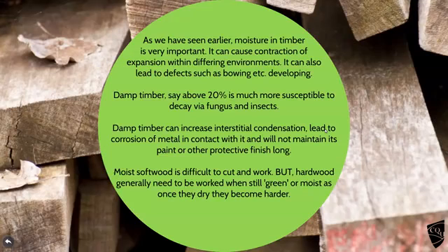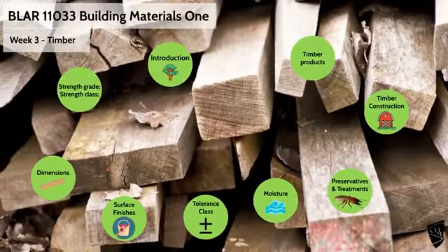Softwood, when it's got a high moisture content and it's quite young, it's very damp, can be really quite difficult to work with. If anyone's tried to use a handsaw to cut quite a damp piece of timber, you know what I mean. The teeth all get clogged up. Very difficult to work with very wet timber. But on the flip side, some hardwoods, if you want to work with them and cut them, you've got to do it pretty quickly after they've been felled and processed, because they get harder and harder as they dry, and then they become really difficult to work with. Green timber, we would call it.